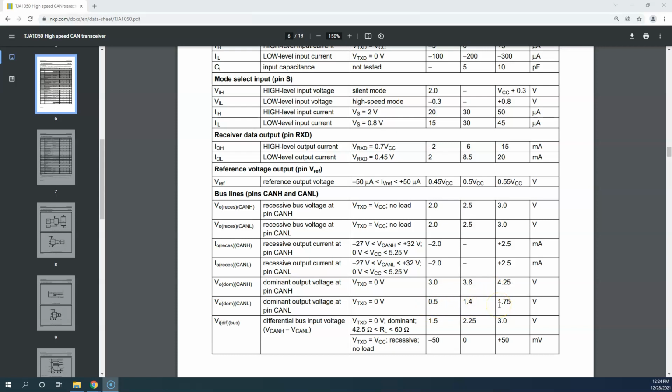What that means is I could go from machine to machine, and if I'm looking for this CAN high on an oscilloscope to be exactly 3.6, it might be, it might not be. And as we'll go through some of the failure modes, looking at the grounds that are on the various controllers, we could see that we could really have some variation in this. So getting too hung up on CAN voltages, getting too hung up on what you see for some level can lead you down basically to a trap, and you'll spend a lot of time looking for something that isn't really a problem. As I said, CAN is concerned really with this differential voltage.